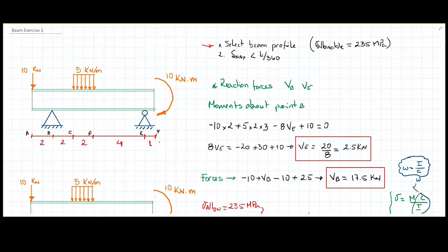Question would be, okay, which L, because we're working with supports and everything. So you're going to have one L1, and that's going to derive at L1 divided by 360, or any other number that you're using for your design. Could be 180.